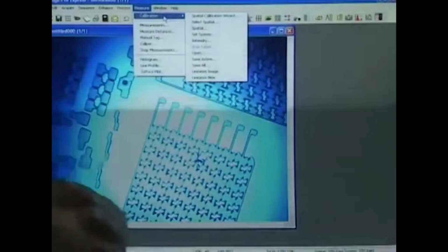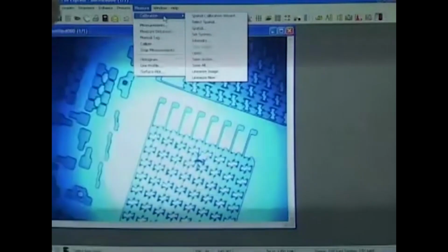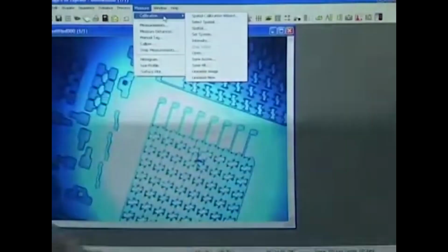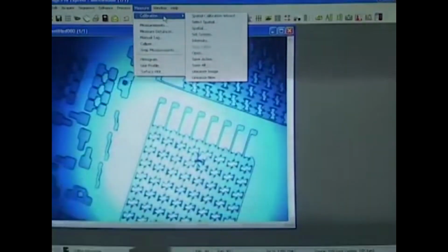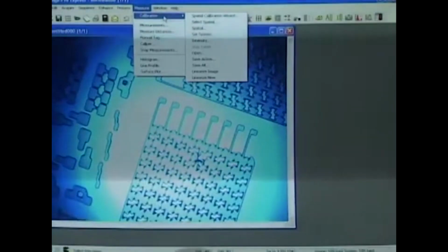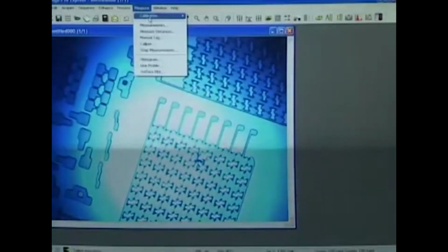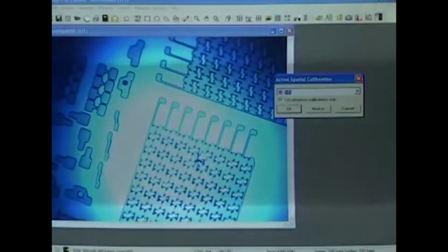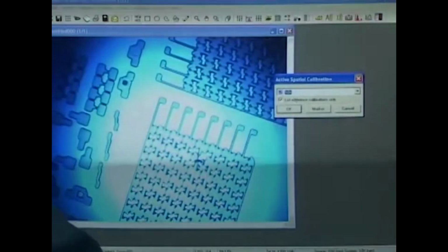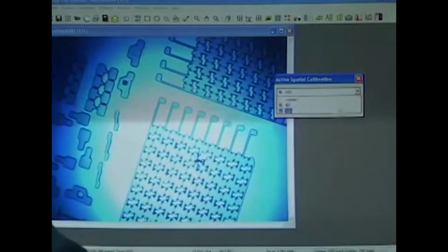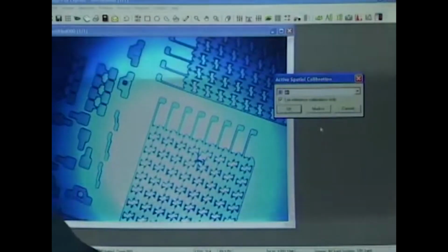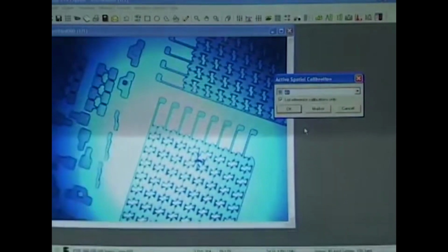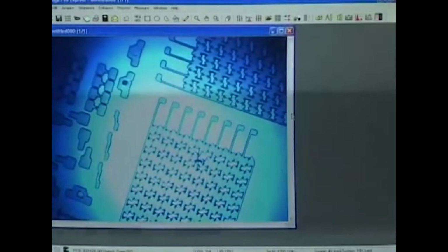So, the magnification value has to be put in the software for it to tell what really would be the actual image size. Whatever sizes it is getting in terms of pixels on this digital image would be converted by dividing by a factor of 4, so that the actual sizes can be obtained. So, I am going to give the system the magnification. It is providing a standard magnification of 10x, which has been the set value, but ours is 4x. So, we go to this drop down menu and input the reference calibration and make it 4x, and let the system understand it is 4x.